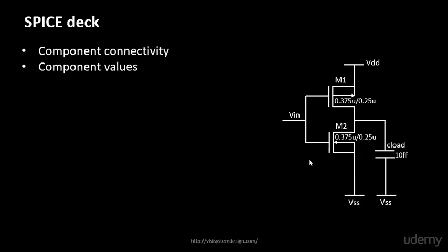There is a scenario where we understand the PMOS should be wider than the NMOS, and we'll come to the reasons why the PMOS should be wider than the NMOS. In this case we'll just assume the values of 0.375 and 0.375 both for PMOS and NMOS. So we are taking the same size PMOS and NMOS and see what happens in the characteristics. Ideally your PMOS should be twice or thrice bigger than your NMOS. By that I mean 0.375 multiplied by 2, in that range.